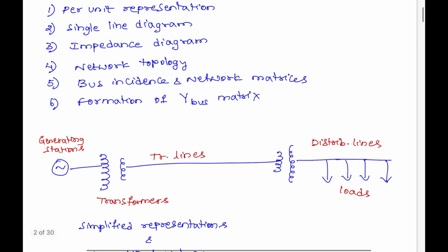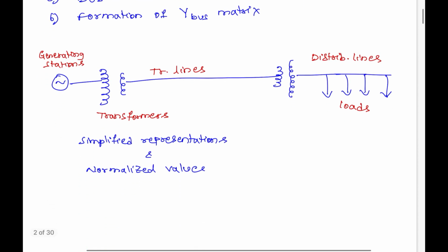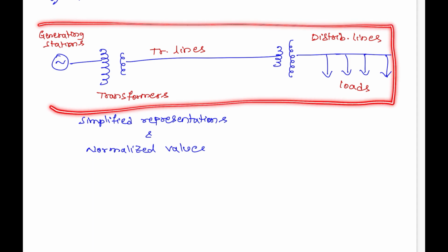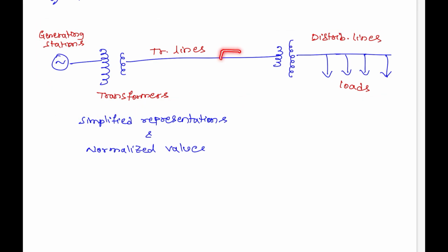The concept is that every element has its own impedance value, which depends upon its own ratings. If the system has one common base kVA and common base kV, we can calculate the impedance offered by the circuit elements so that we can provide the protection at appropriate locations.